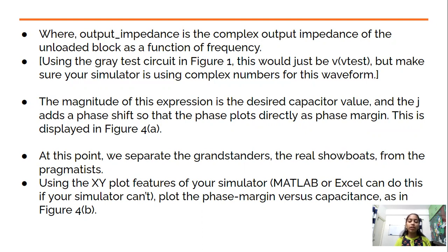At this point, we separate the grandstanders and the real showboats from the pragmatists. Using the XY plot features of your simulator, or MATLAB or Excel if your simulator can't, plot the phase margin versus capacitor as shown in figure 4B.